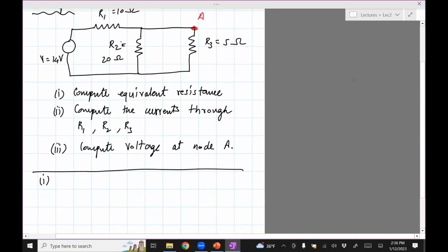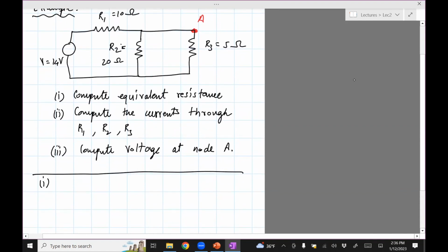Okay. So when you're doing this, you want to avoid starting with loops with voltages, because you just don't want any voltages to affect the computation of resistance. You start with things where there are no voltages. So things on the right side are nice because there's no voltages. This trick usually works when you don't have voltages. If you had a voltage on the right side, then it becomes hard to do what I'm going to do. Okay, so let's start from the right and work our way to the left.